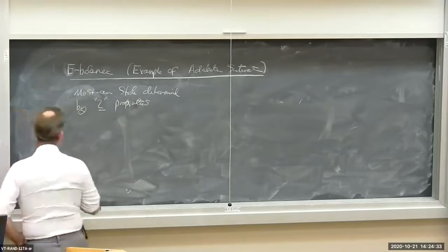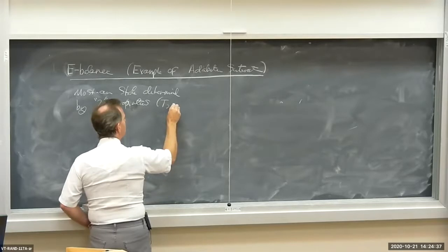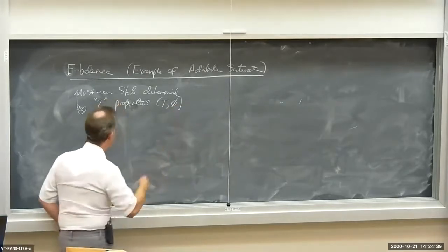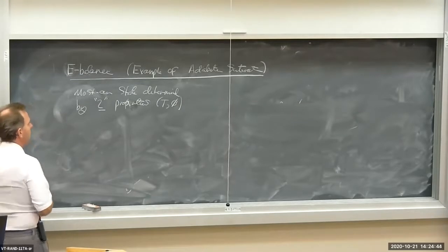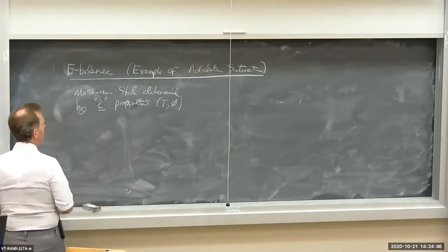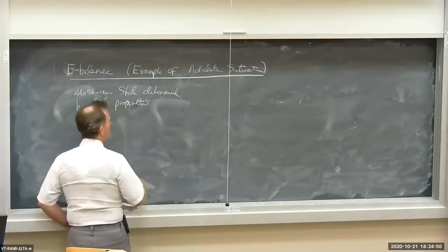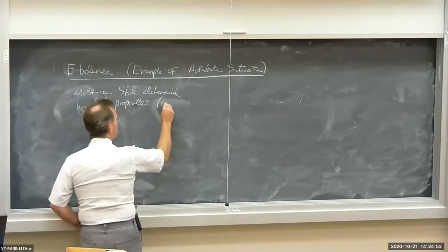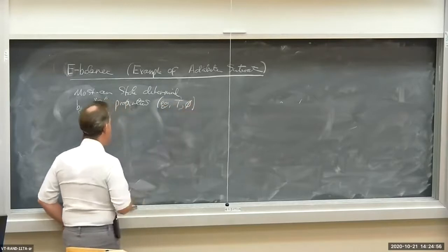An example would be, let's say you know the dry bulb temperature and you know the relative humidity. That puts you on the psychrometric chart. So moist air state determined by two properties. For example, it's not always temperature and relative humidity, but e.g. temperature and relative humidity.